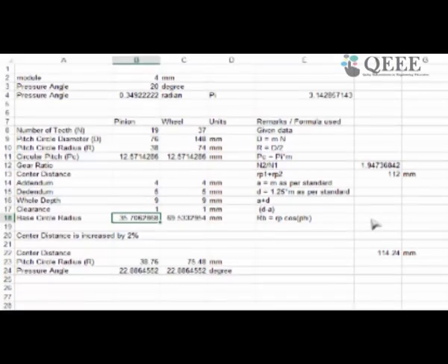So, what you see is that this 2% change in the shaft distance has increased the pressure angle by a little more than 2 degrees. From 20 degrees it has come to 22 degrees. It is quite a bit in terms of percentages, but a 2 degree change in pressure angle would really not matter. Other than this effect that the pressure angle has changed, there is nothing lost in this process. That is why we say that involute gearing is a robust mechanism, in the sense that it is able to accommodate any inaccuracies associated with the process of assembly.